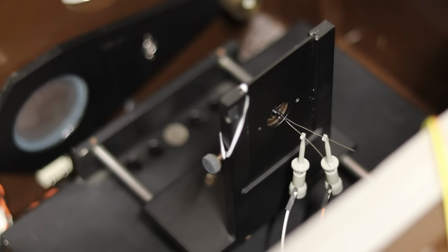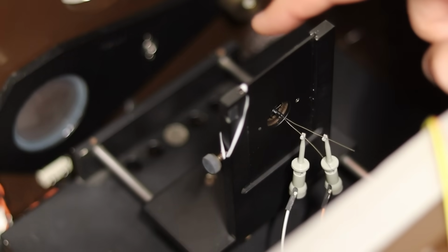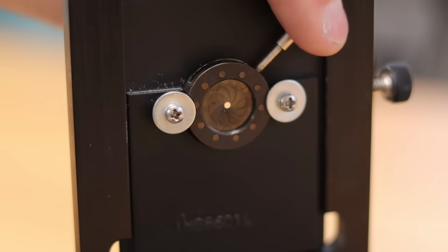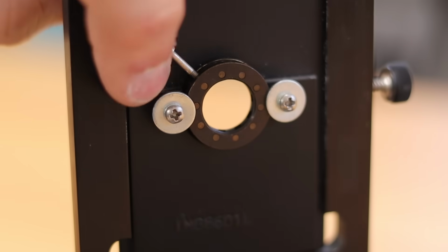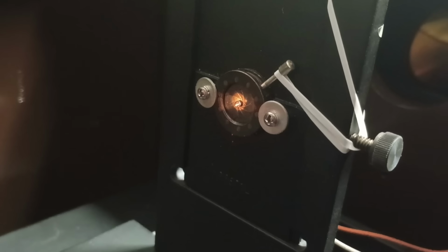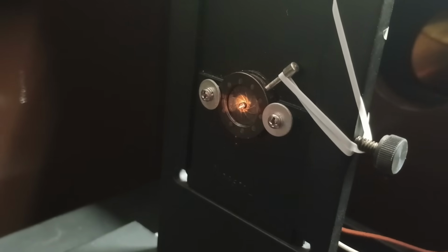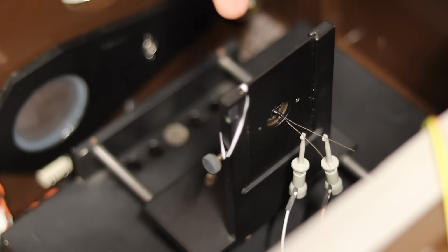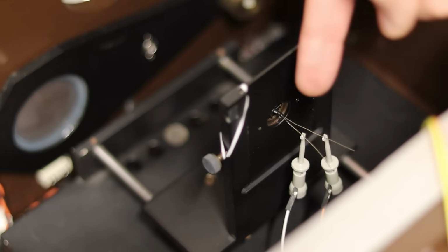And my solution for that is a little MacGyver-y. I have this card right here that is an adjustable iris. It's got a little lever on the front. And all I did was I put the photodiode in the center of that iris and then used a rubber band here to close the iris on the photodiode. That holds the photodiode perfectly centered in the optical path. Then I just gotta put some little clips on the leads coming off of the detector, and that's it. That was like a super easy setup.